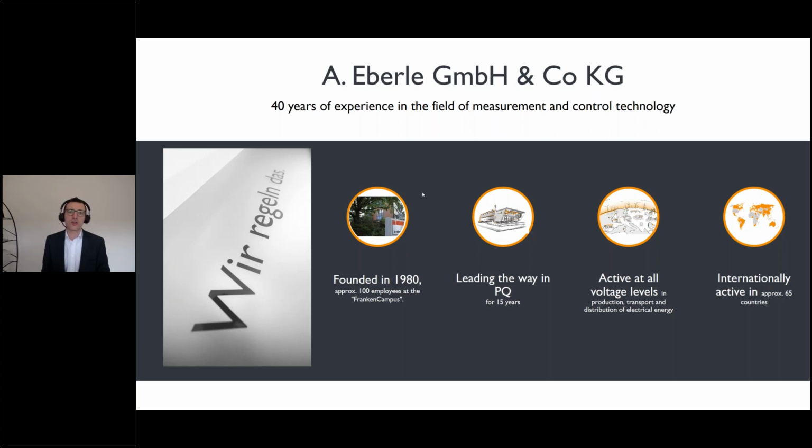because in the low voltage segment, the most influences will occur during the energy transition. As an example, we also have a power quality solution, which has the opportunity to regulate the voltage stability in the low voltage grid. Its name is LVRSys, so low voltage regulation with a reaction time of 30 milliseconds.